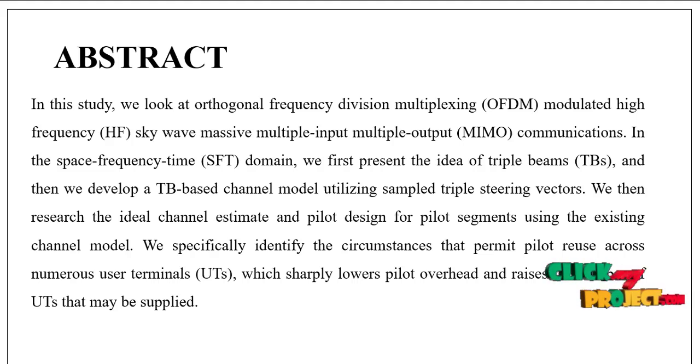We then research the ideal channel estimate and pilot design for the pilot segments using the existing channel model. We specially identify the circumstances that permit pilot reuse across the numerous user terminals, which sharply lowers the pilot overhead and raises the number of UTs that may be applied.